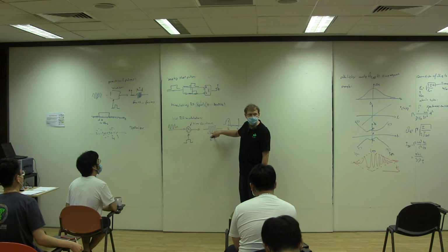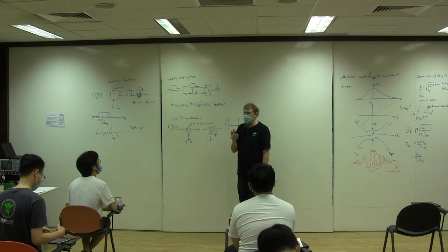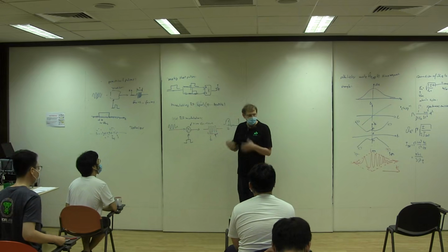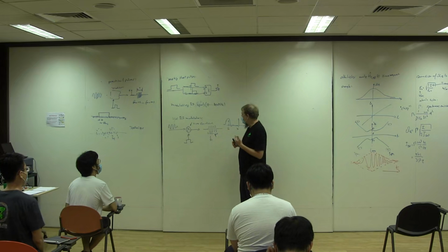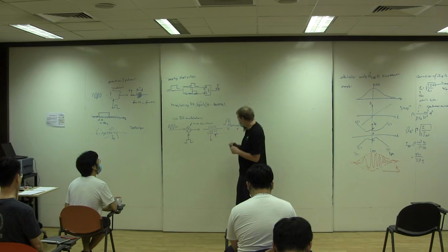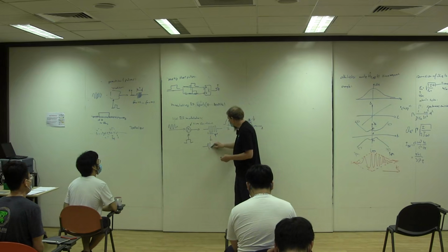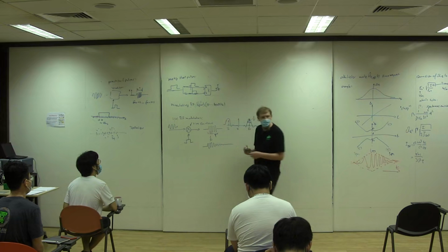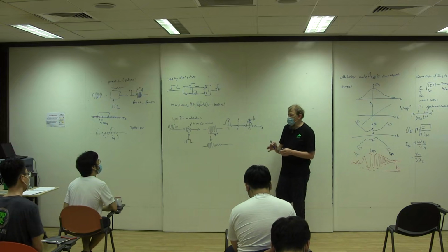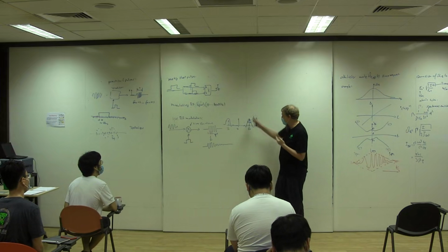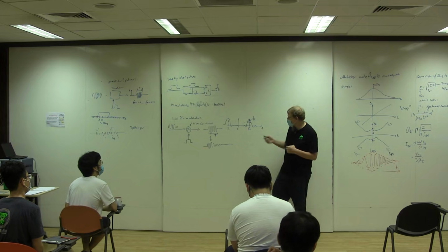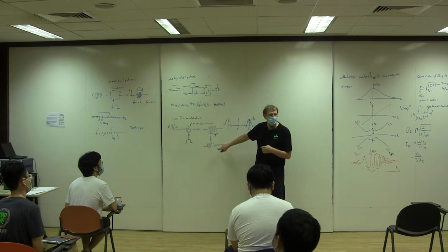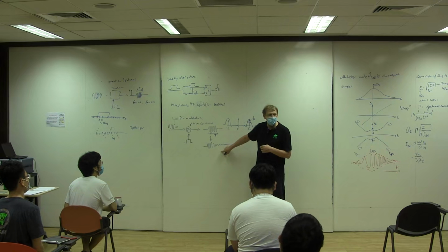So if you use a synthesizer to make a particular wavefront, check carefully whether you actually get what you want to see, because you may not be aware that there are funny filters in the system that make sine waves look nice on average. But once you have a pulse sequence, the wavefront you get may not look like what you expect, and it may take forever to ring down, simply because you have a filter that cuts off a particular frequency part. So this can be quite tricky. In a practical scenario, always check whether whatever you get out of your system looks like what you think it should look like.